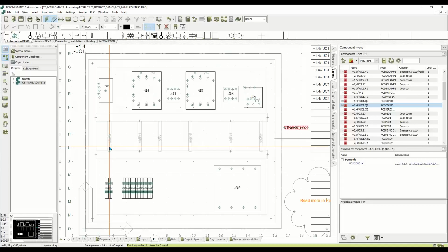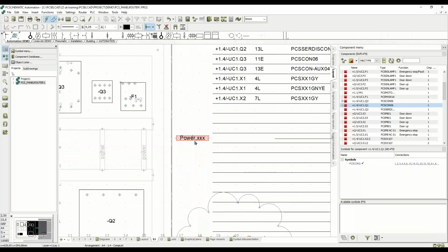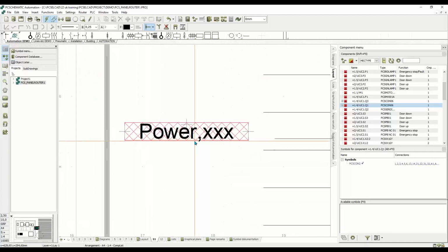So when I put in my wire trays, I can assign them to one or more routing classes, and then they are only open to those classes, or I could open them to all classes, and that would be okay. I can go in and say which classes are allowed to be in those trays. But then sometimes I also need to put a full stop in.